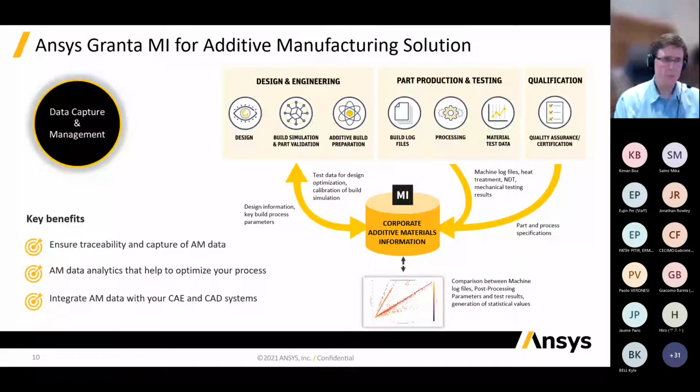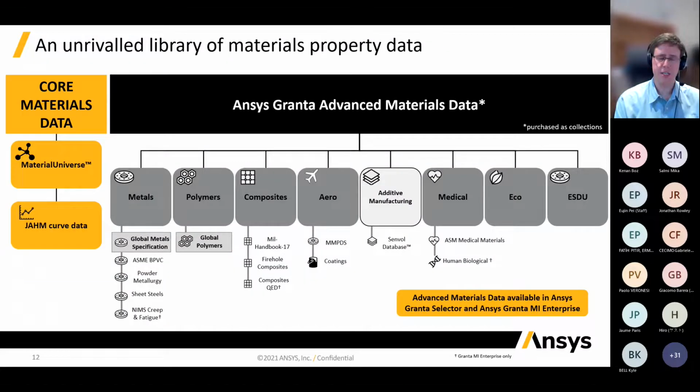And the other thing I would emphasize, it's not just about the additive manufactured data. So again, if you have data on your additive manufactured components and also reference data from industry, this is brilliant. You can start using this to make decisions, but often that may not be enough in and of itself. You may need data on the corresponding conventional materials that are in contact with these. You may need to be able to do a comparison, or the properties may simply not be available for your desired feedstock. So taking an example, you may have a titanium 6-4 feedstock, and this feedstock works fine, but you don't have full properties for this particular feedstock, but you do have properties for the parent material. So you can start using that as a reference point and a comparison.